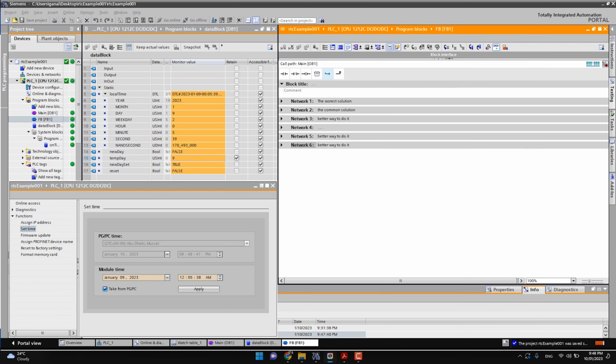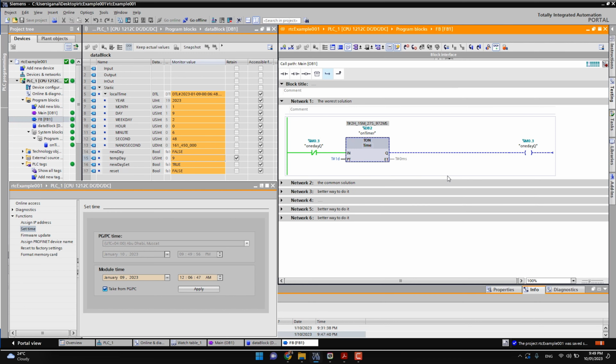So as we mentioned, we need some daily triggers so we can save our calculations into another space, like structures, arrays of days, or any other variables. So in our first example here, our friend is simply using an on-delay timer and negating the output back again on the input, which is a very classic way to keep the timer running forever and generating a pulse once it finishes counting. And you'll find it in several applications for the second clock.